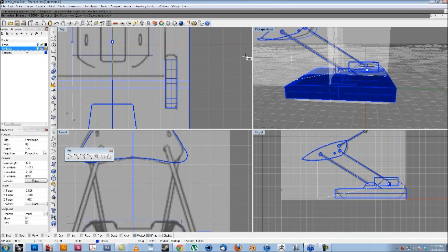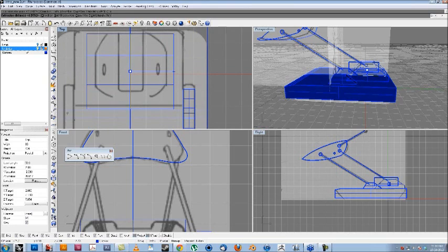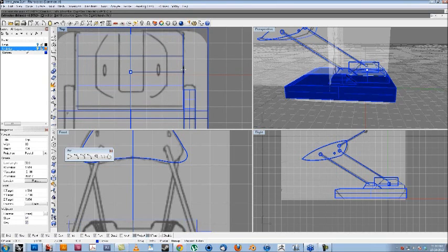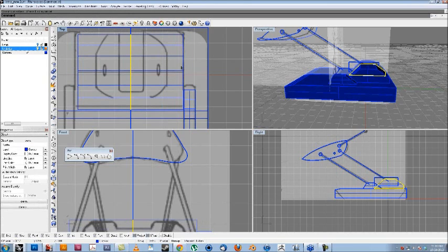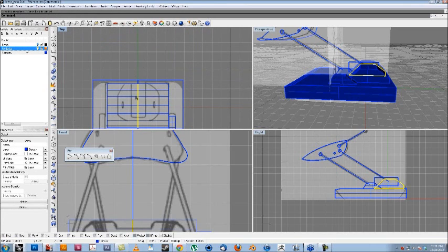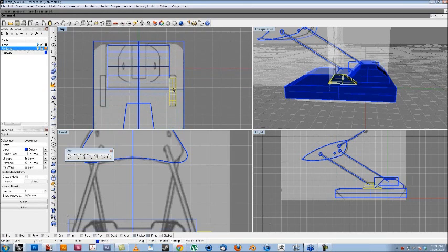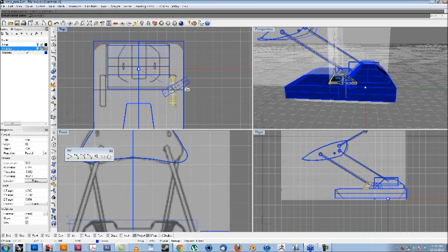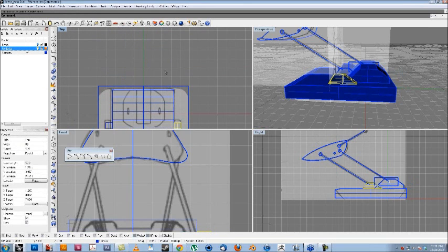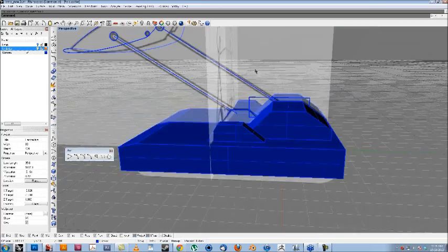And you'll notice that I keep going back and forth between extruding with both sides turned on and both sides turned off. It's just a matter of the fact that I built this thing on the 0 axis, so it's like on the y-axis perfectly. If I have something on one side, I'm only going to have to model this once, so I can now mirror this along 0 and get it perfectly into place, and I know it'll line up perfect.